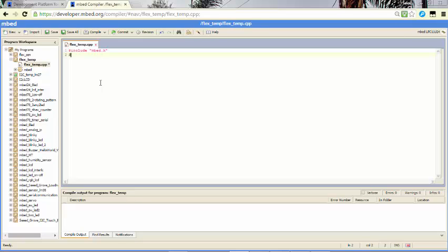So how to define it? We have to write Serial as serial communication. We give some serial name and define the pins, that is USB TX, USB RX, that's it. So we define the 2 pins, that is the transmitter and receiver. Then let's go further, defining the analog input pin, whatever analog output is coming from the sensor, you have to take as the input of the analog board.